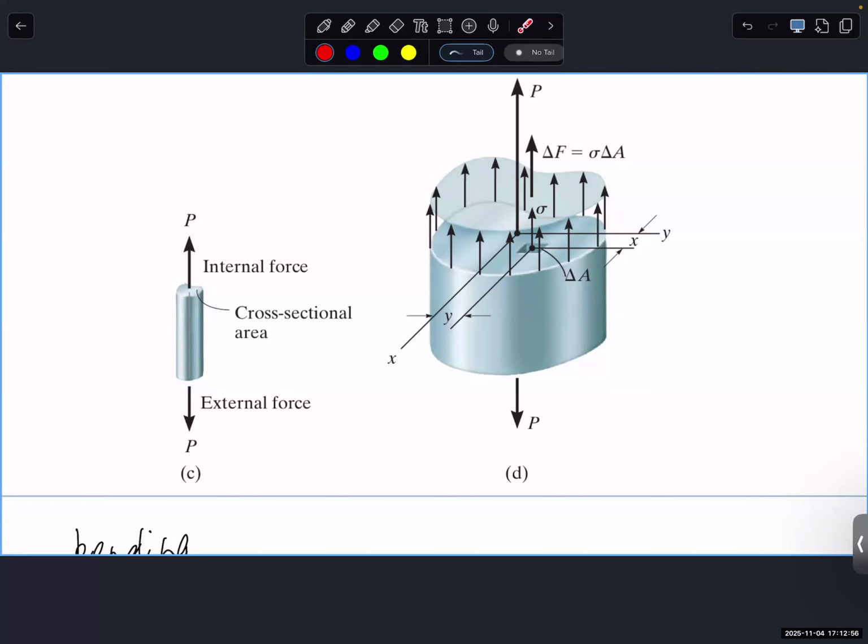But it doesn't mean there's no deformation in the bar. It can elongate. It's the same as a spring. If you have a spring system, you can pull it, and there's elongation, very visible deformation, right? And then you push it, it has contraction. So force equilibrium doesn't mean that displacement is zero. Deformation depends on how deformable your material is. In real life, we don't really have a real rigid body. Everything is deformable. Some materials have higher stiffness, some have lower stiffness, so the deformation is more visible or less visible.